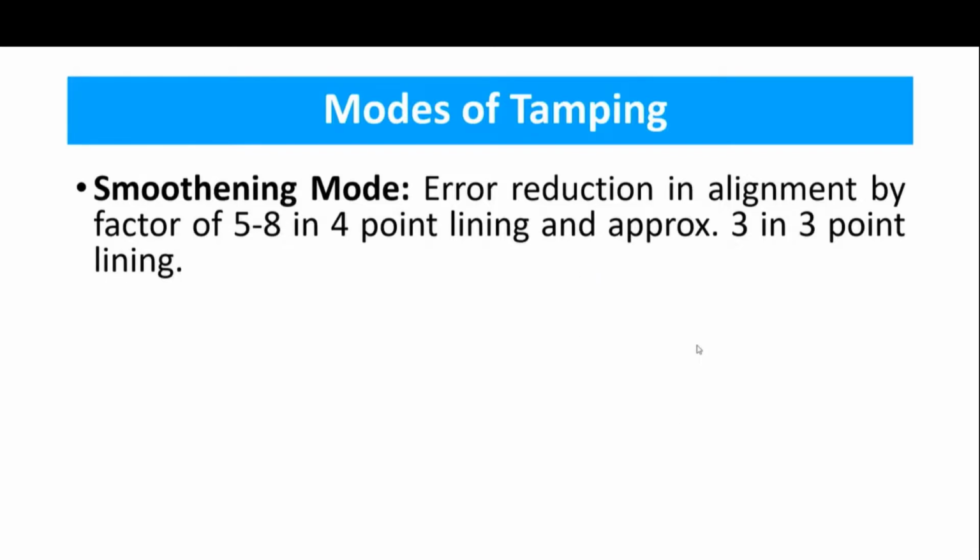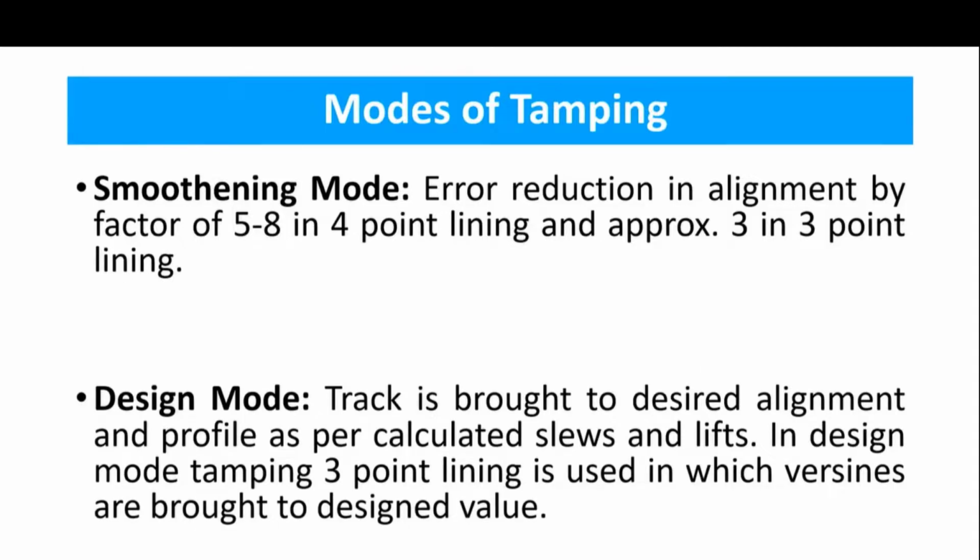We also do the design mode tamping, but the present method of doing design mode tamping is more of relative, like realignment of curve and then alignment correction by theodolite or some optical instrument for the straights.